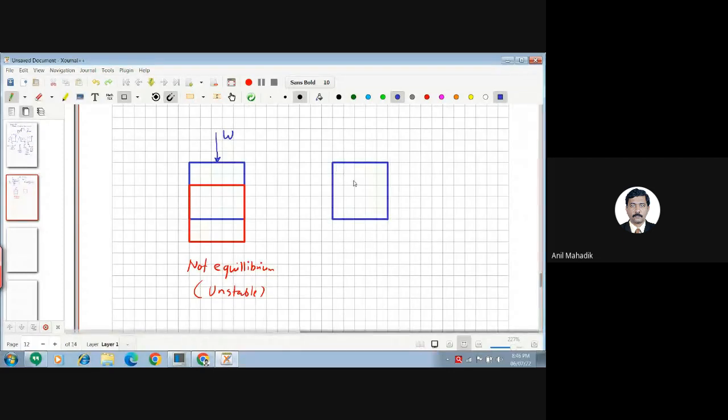Now you might have seen that I'm using this graph paper. One more point: I'm using this graph paper because it gives me the reference lines, horizontal and vertical lines, so that I can draw the sketches in a more appropriate way. So whenever you do manual calculation on paper, I suggest you use graph papers like this, square ruled pages. This is general practice internationally. If you are doing any work manually in any structural engineering office, they generally use square ruled pages because it helps you draw sketches to scale and appropriately. It is not necessary that everybody is a good artist. People may not have good sketching skills, but if you have these grid pages, then at least you can do the sketches appropriately to scale.